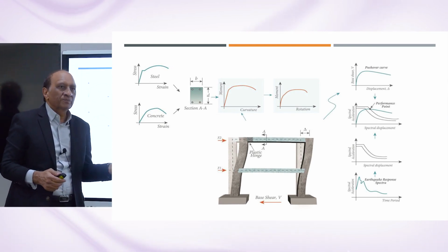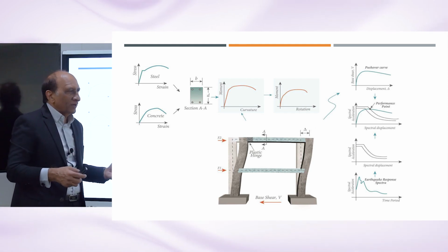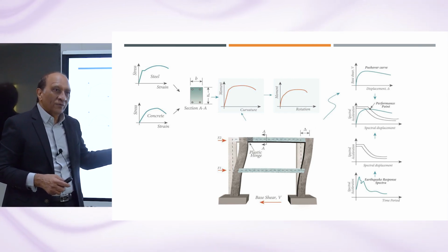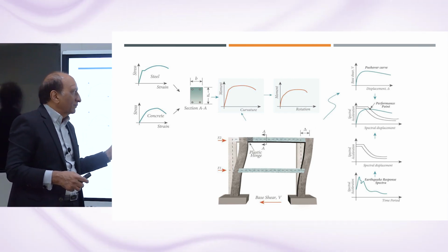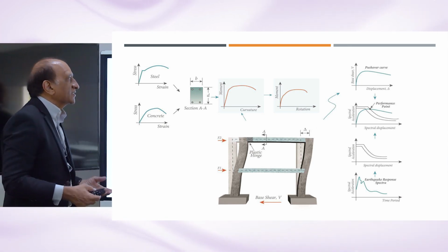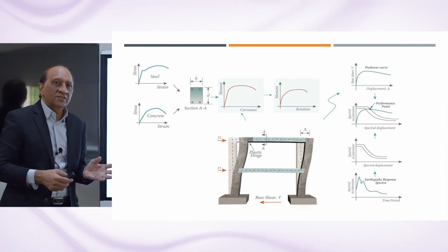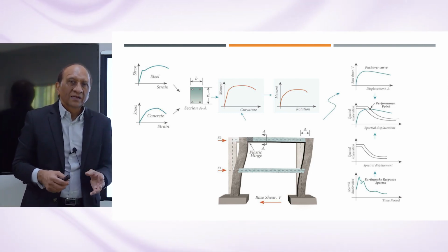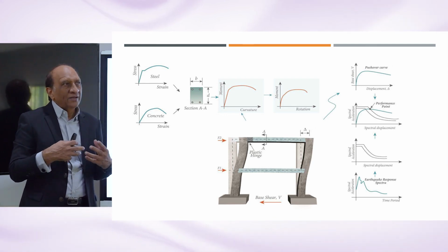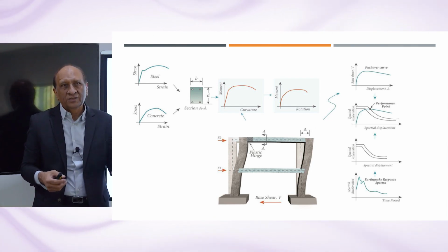Of course, now most of the time we use full nonlinear time history analysis, and we use more advanced methods, but this is still very useful to do a pushover analysis to understand the nonlinear behavior and how it will interact with the demand or how it affects the demand. So this is a summary of where the moment curvature fits into the overall evaluation of a structure, or the evaluation of the seismic response, or any load which goes beyond the traditional load.